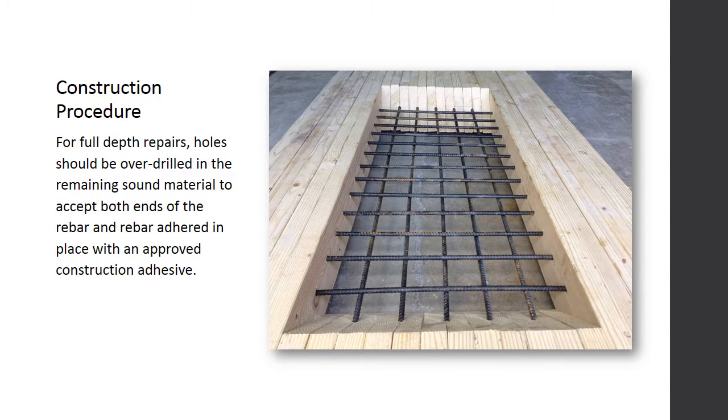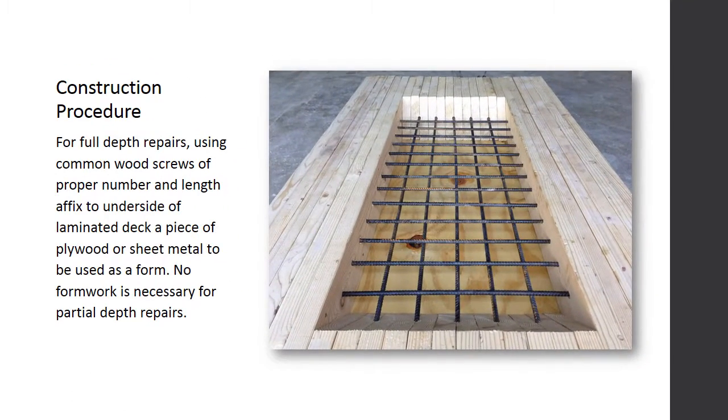For full depth repairs, holes should be over-drilled in the remaining sound material to accept both ends of the rebar, and rebar adhered in place with an approved construction adhesive. Using a sufficient number of common deck screws, affix a piece of plywood or sheet metal to the underside of the deck to serve as formwork. For obvious reasons, a partial depth repair does not require this step.